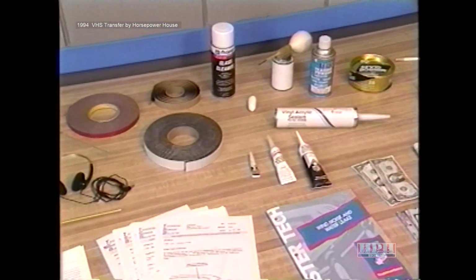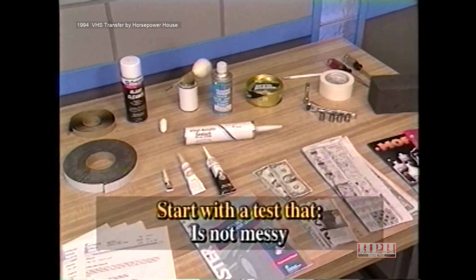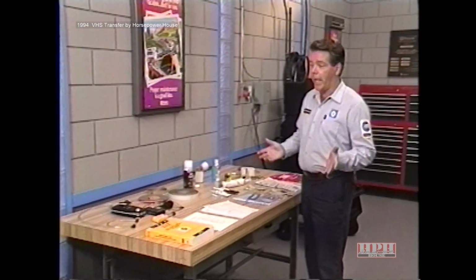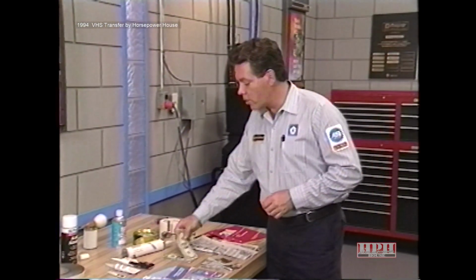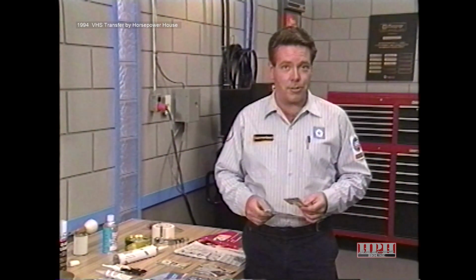But we can tell you that you should start with a test that best corresponds to your condition, one that is not messy and is simple to perform. One procedure, the paper test, is very simple to perform and is especially effective in checking door glass and quarter glass that has direct contact with roof rail weather strip. It can also be used to check deck lid weather strip and convertible top seals.